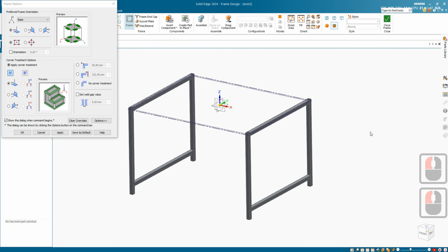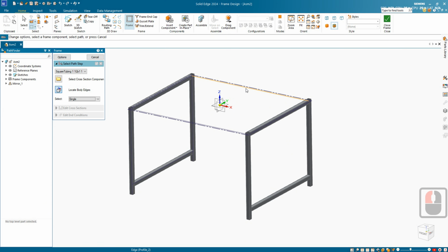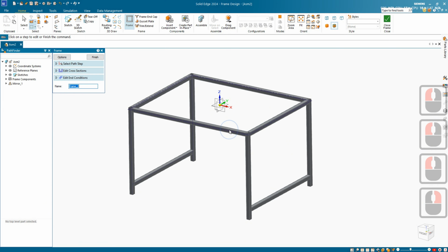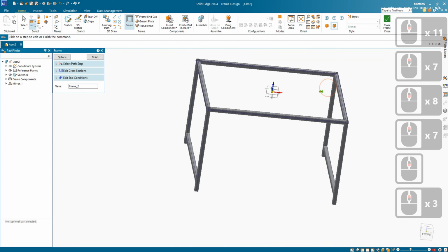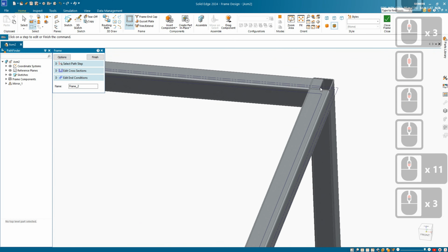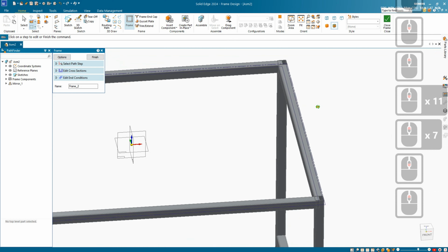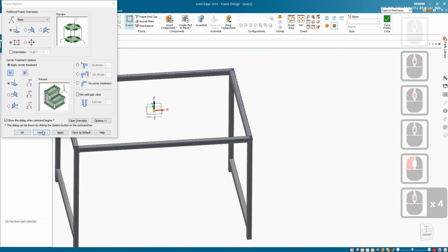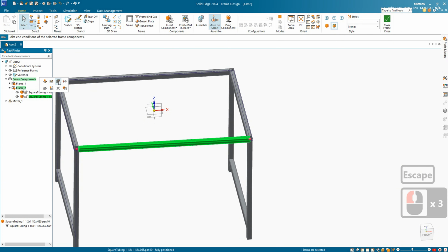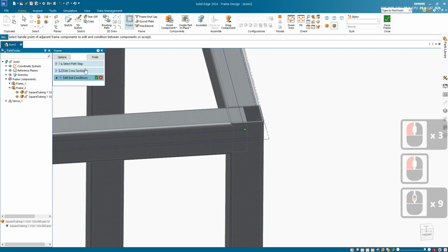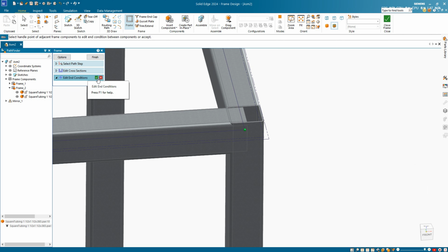select frame, and then just select the crossbars over there. Now you will see sometimes the software will trim your bar up to an existing one, and sometimes it won't. You would need to create a plane in order to trim that bar to it. Unfortunately, the software seems to not want to select the face as being a plane when you want to trim off that interfering bit.